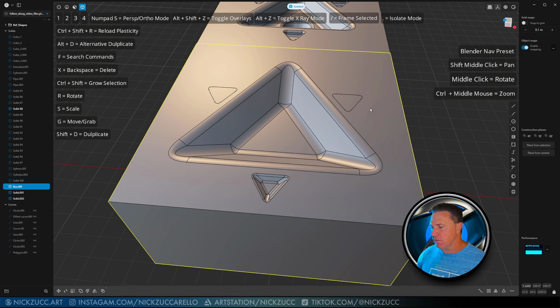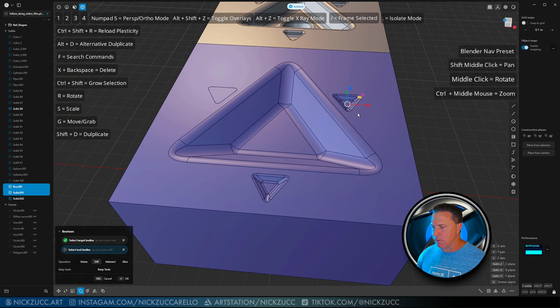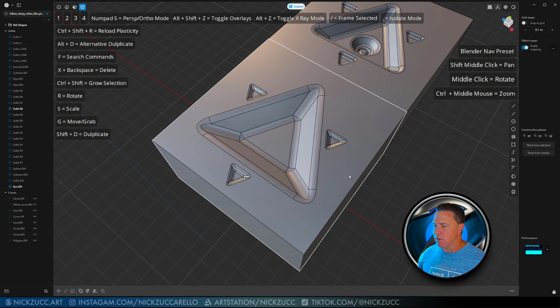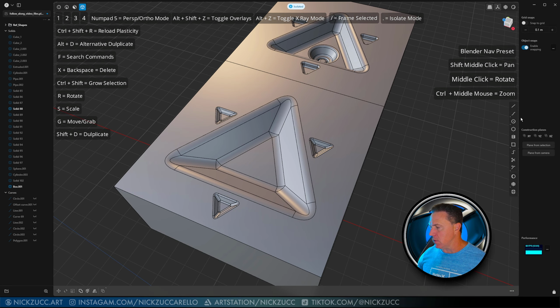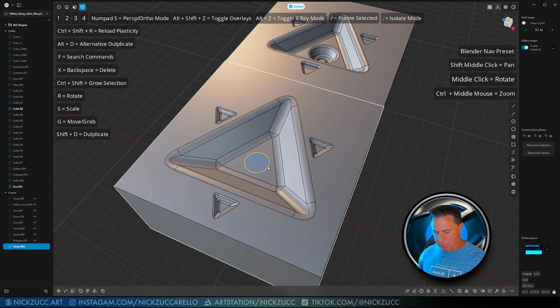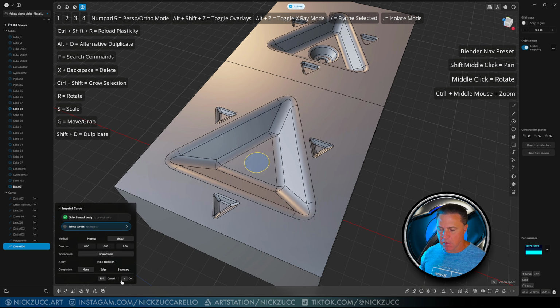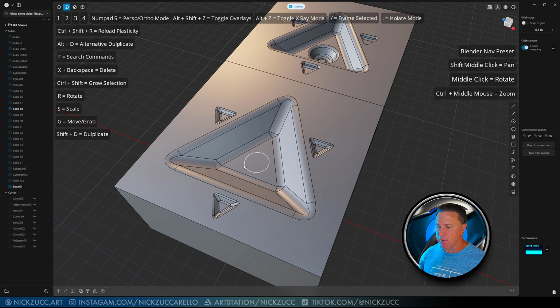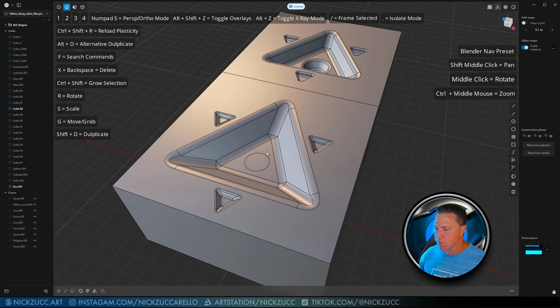We can select this first, hold down Shift, select this, tap Q. If we hold down Shift, we can add this one here and hit OK for that. And then the next part, it's going to be pretty easy. We're just going to do a center circle, click and drag out from here, like this. And we'll do Shift I, select our body, imprint it on there. We can tap 2. We can either delete it or we can tap H to hide. It's up to you what you want to do.